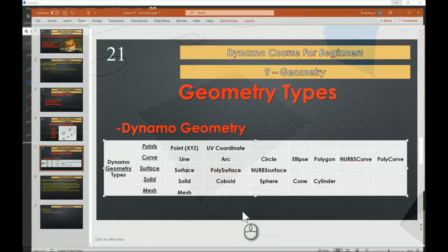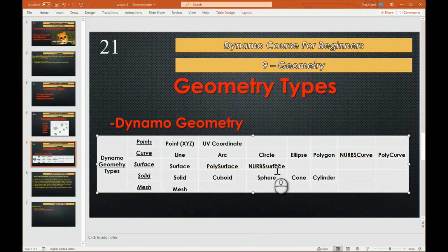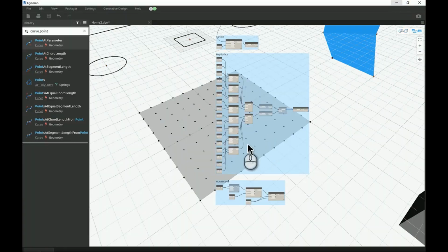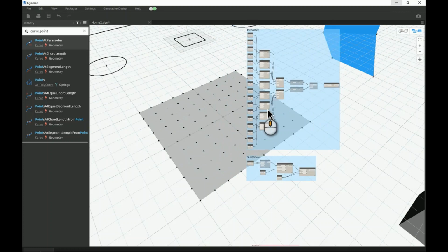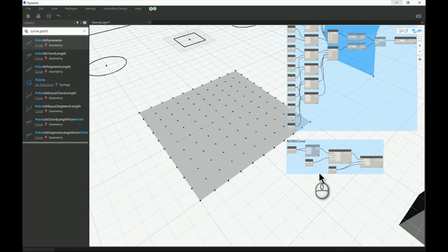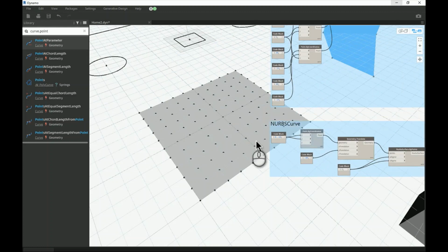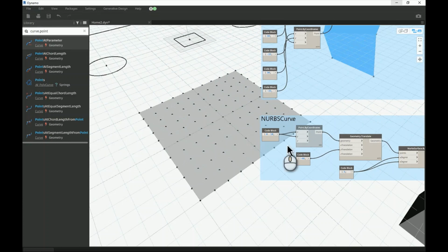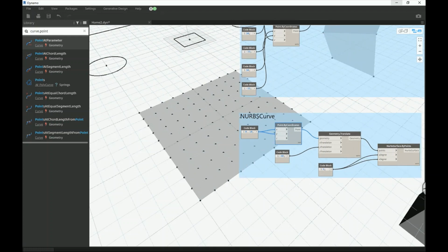They are way more advanced, and they allow you to create seriously more complicated geometry. They even structure differently. They are expecting an array of points. So here we don't deal with four points or the external perimeter point or the patch point, whatever you want to call it. Here I'm just creating points, and I use them just like an array, and then I use that to create the surface.